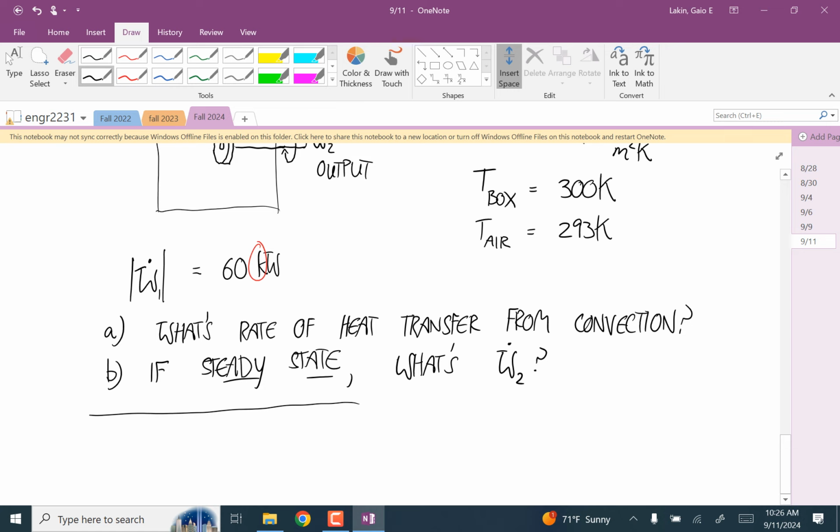Okay, before I go into these, anyone remember what steady state means? What does that tell us for this problem? That term is going to come up pretty often on these. Doesn't change. The properties don't change, which means nothing on the left side of the first law, those rates of change, are all 0. So E dot is 0. So kinetic energy dot is 0, potential energy dot is 0, and internal energy dot is 0. They don't change in time.